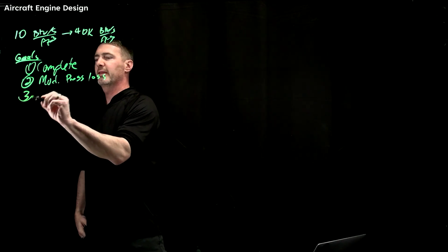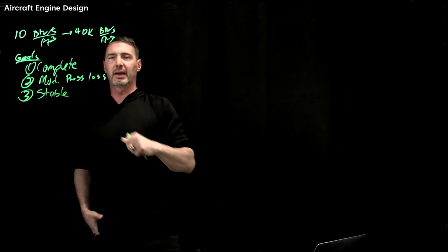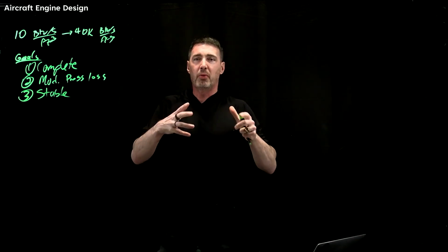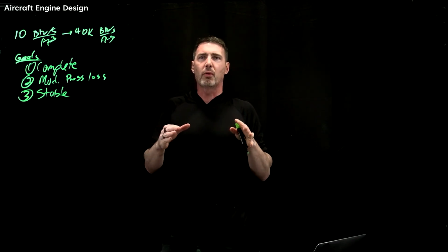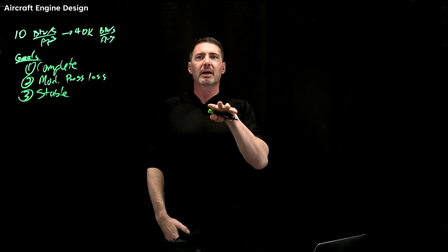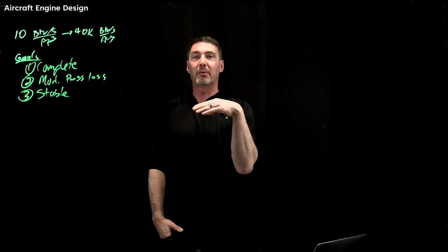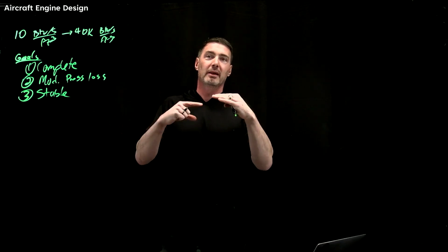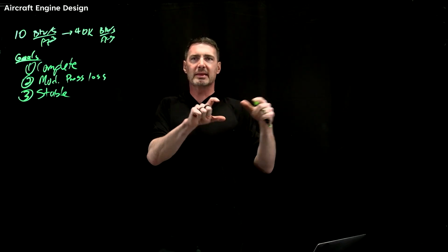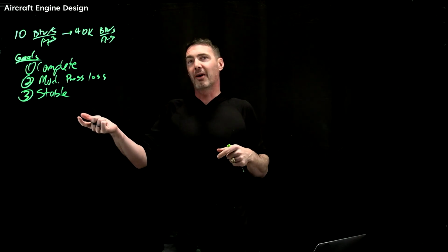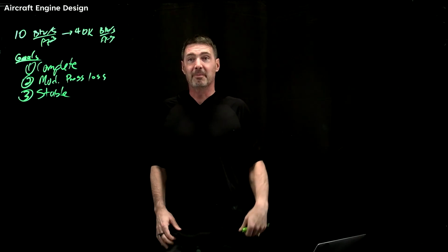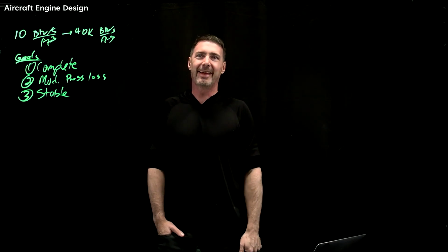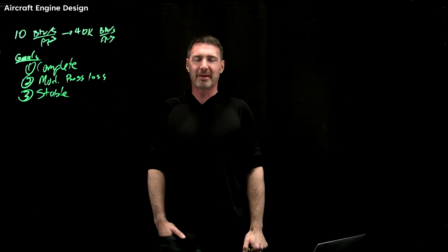Third one is stability, and this means no flame out. Stay stable. I heard a story of an engine design that was all the way to the point where either this was initial trials with the aircraft, or maybe they had already delivered them to the fleet. The story was an aircraft turned to get ready to take off, and there was a gust of wind from behind. Normally an aircraft is turned facing the wind, and so either during taxi or something like this, the wind blowing backwards went up the engine and flamed out the combustor, so they had to restart the engine. So handling a gust from behind going back up the engine, they had to do a bunch of changes, and I forget what engine company that was.